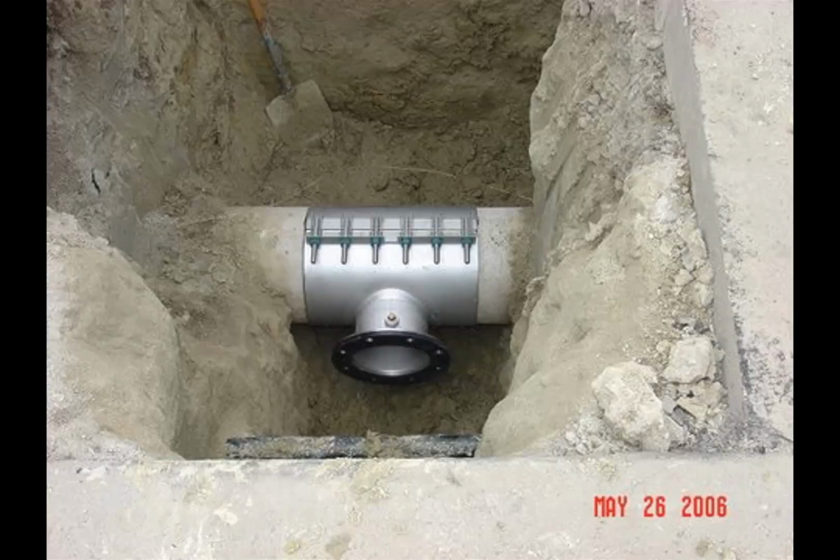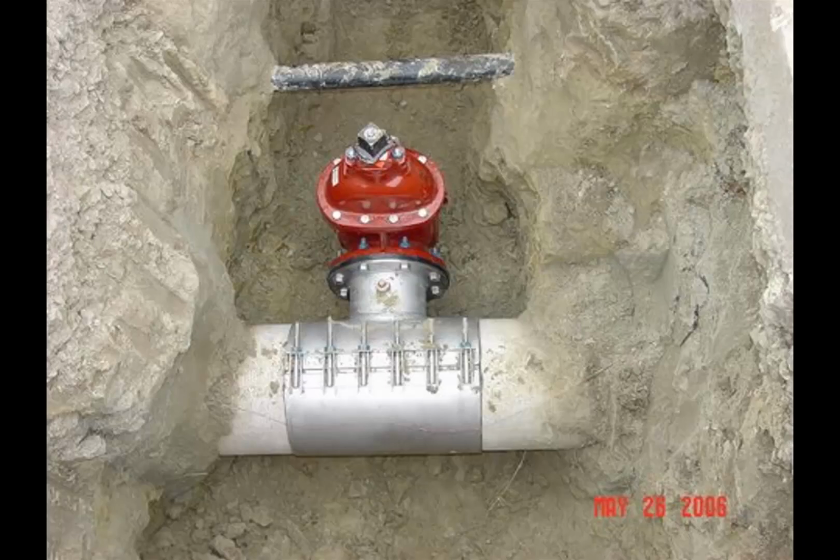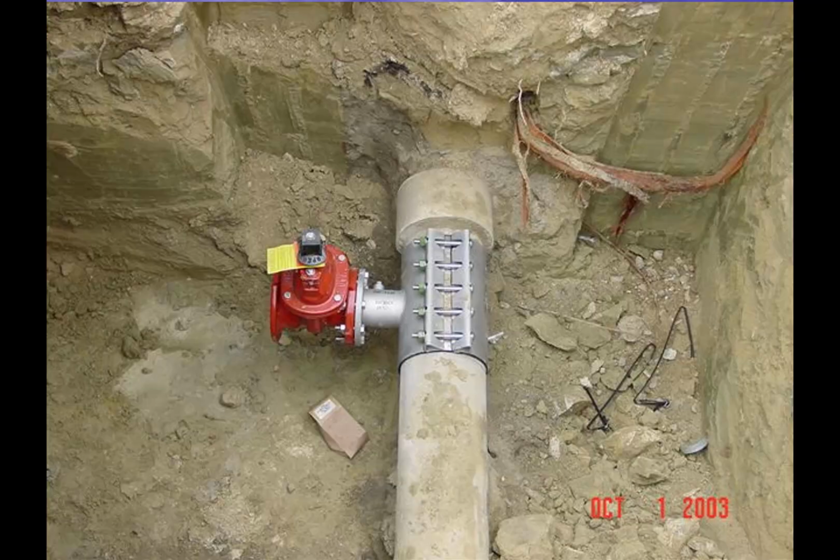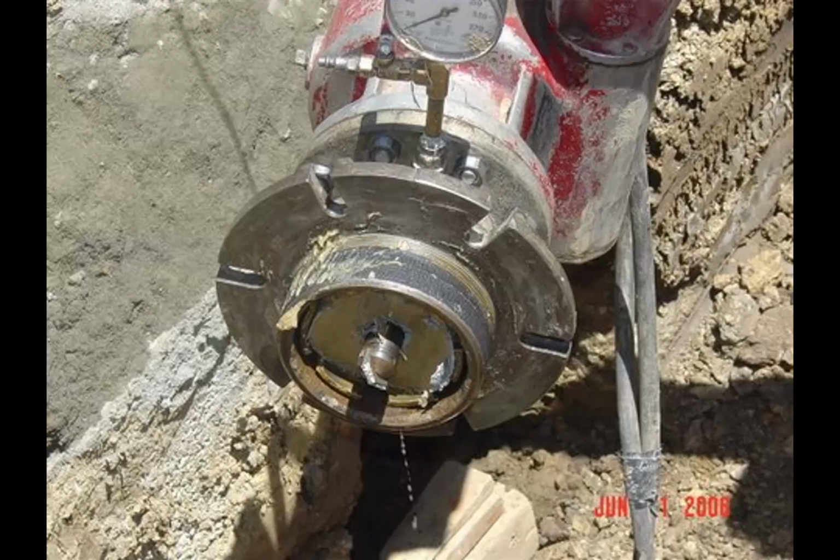So we can take a look at some of the components. There's that fully encapsulating tapping sleeve I was talking about. With that sleeve that goes all the way around the pipe, it's providing some structural support. So even though you're removing a portion of the wall of the existing pipe, the sleeve supports the pipe to provide the structural integrity for the portion that was removed. You have a tapping valve bolted up to the sleeve. And then this is a close-up view of the cutting end of your drilling machine.